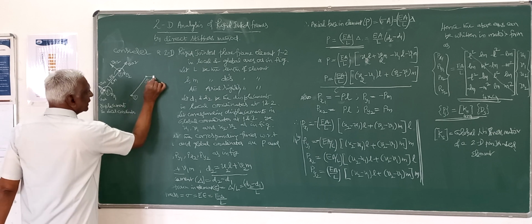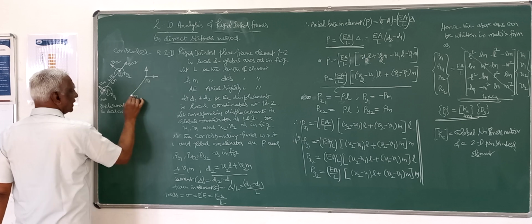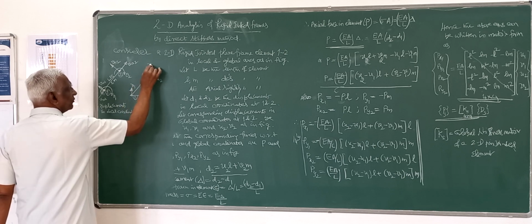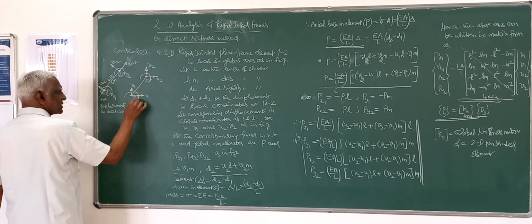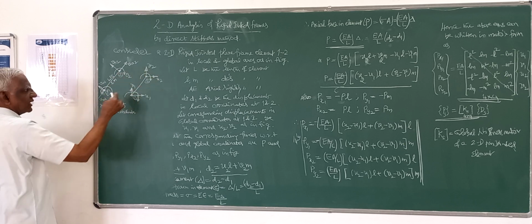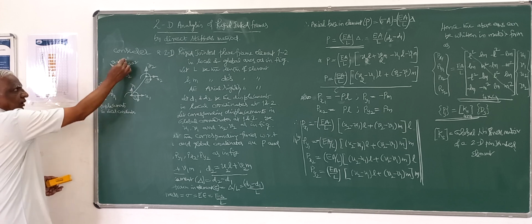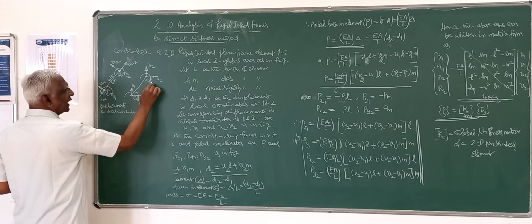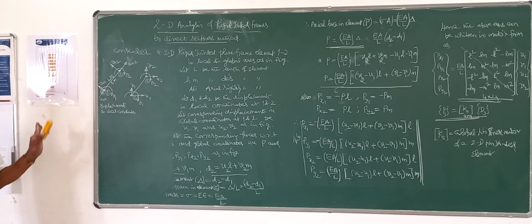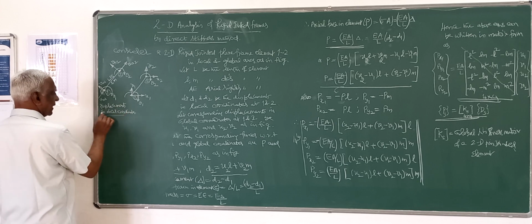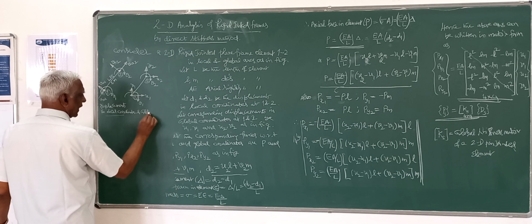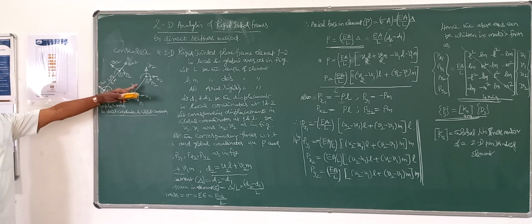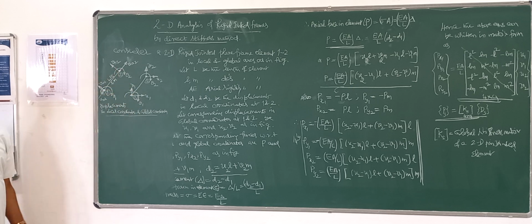So here again, same member in global coordinates, displacements like this with respect to global axis. Here I will call these U1, V1, U2, V2, and of course rotation about the z-axis. The z-axis for this global axis is also the same. There is no change. Even for the member local axis, the z-axis is the same. So these displacements I can take as the same, θ1, θ2. It is about the same axis. That is displacement in local coordinates and global coordinates. I have marked here: this is local coordinates, this is with respect to global coordinates. All displacements I have marked.